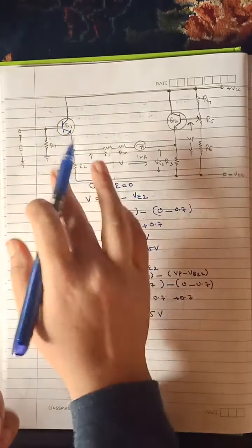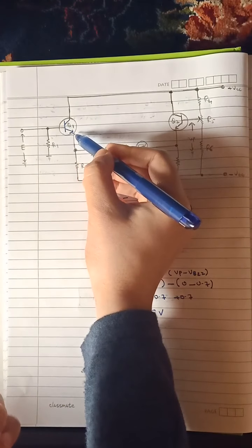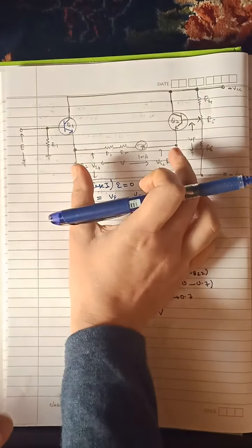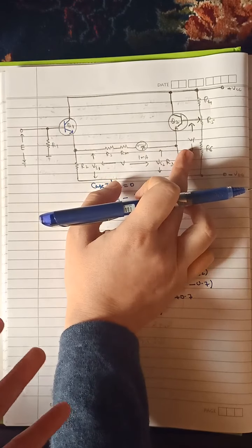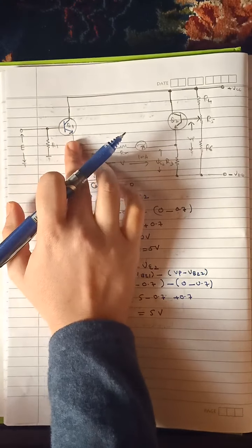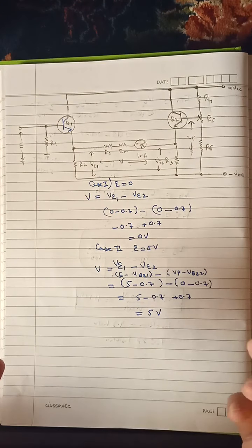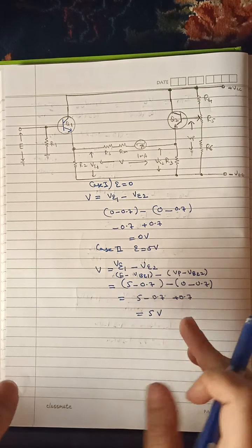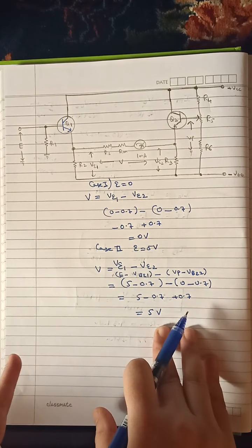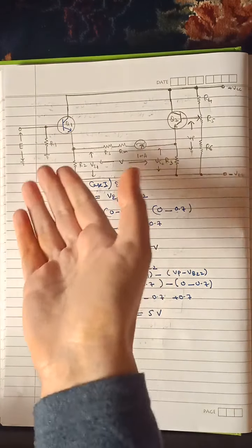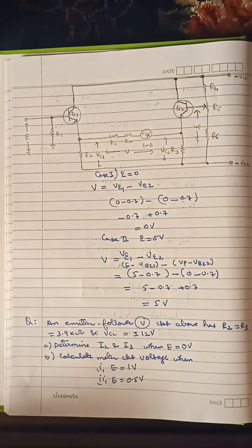But now since we are using two transistors connected opposite to each other, that means if here there is a plus 0.7 volts drop, here there is a minus, because we have to take the difference, these two voltages will cancel each other's effect out, or this error will compensate for this error, and in the end our error is actually corrected and we will have the correct value of the reading. So this is actually the practical circuit where there is no error introduced or error cancels. Errors in the two transistors or drops in the two transistors will cancel out each other's effect.